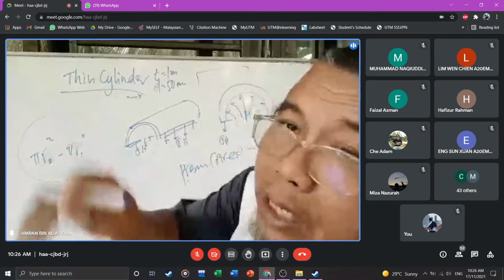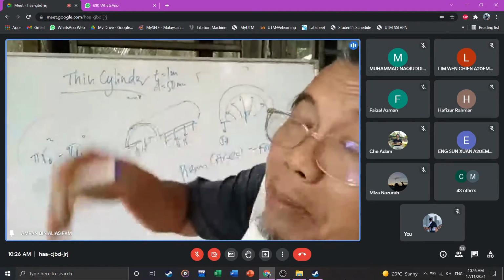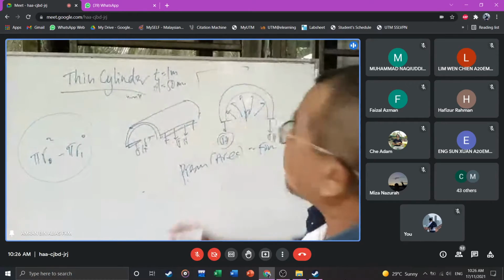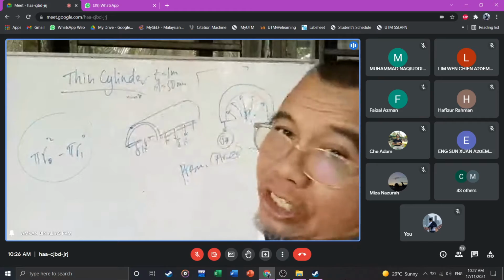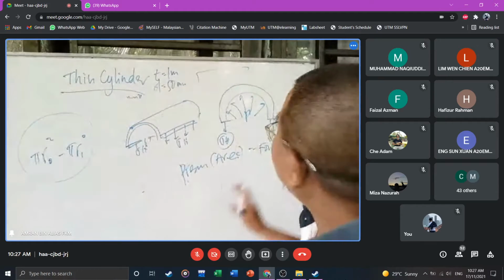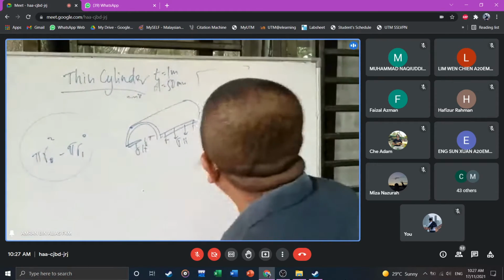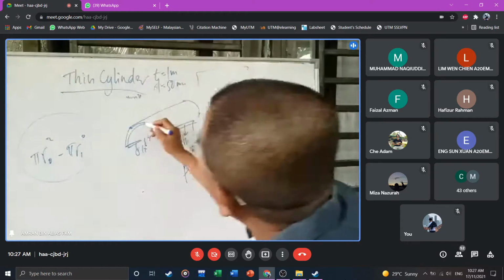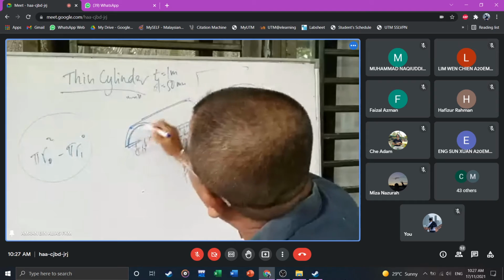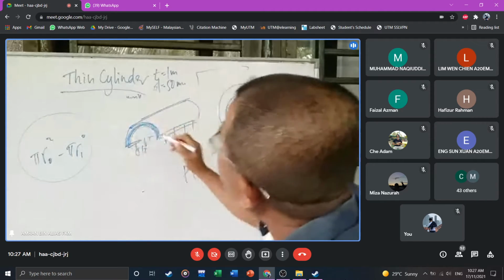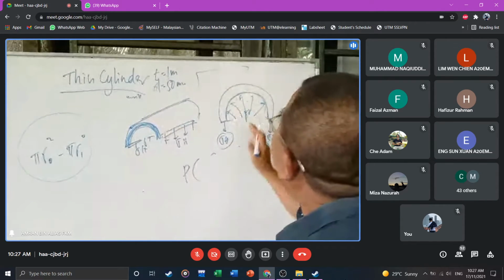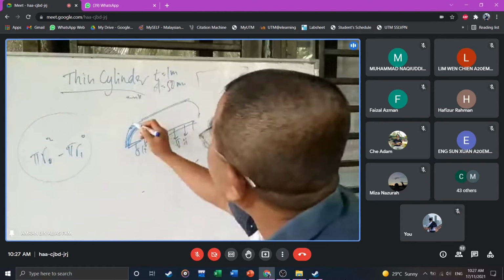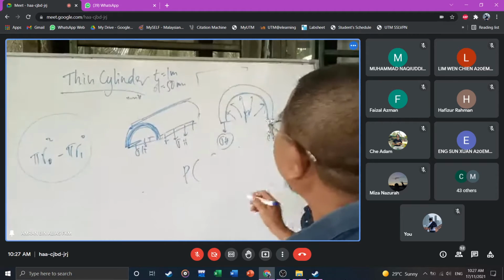And then what is pulling down? The skin body, the aluminium can body is pulling down, because we draw sigma H in the direction of that up, hoop. So what is pushing up? The pressure pushing up. What is the area there? Because this length there, there is a curvature area there. So what is the total length? The area must be that length times that length.